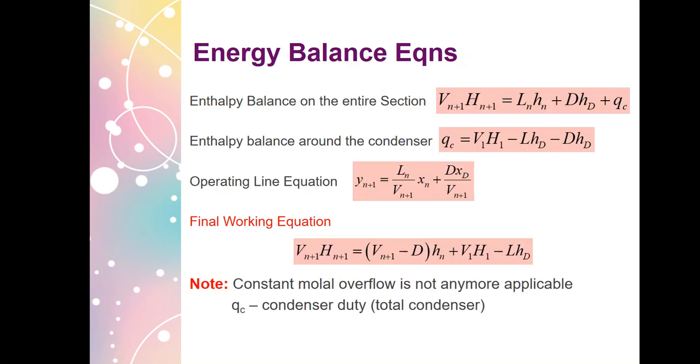Okay. As for distilling columns, we have energy balances for the column, and we have this equation available. This is taken from McCabe. This equation allows you to determine the condenser duty, or the amount of heat that is to be absorbed by the cooling water in the condenser, so that it will be able to condense the vapor, or convert the vapor into liquid.